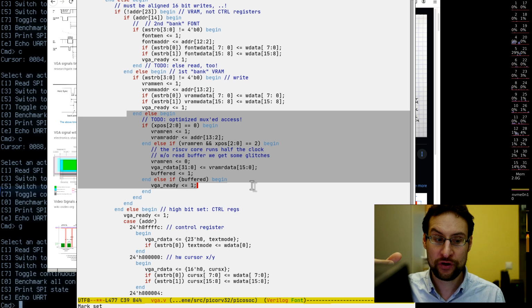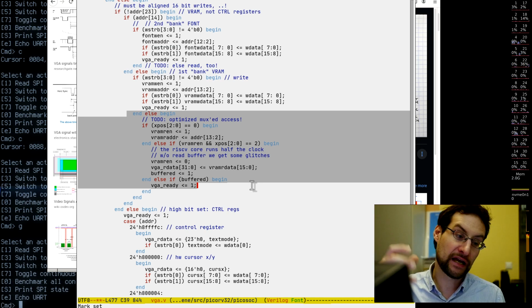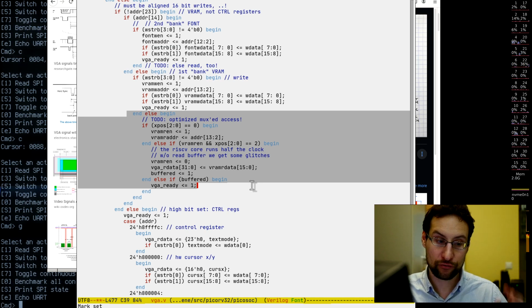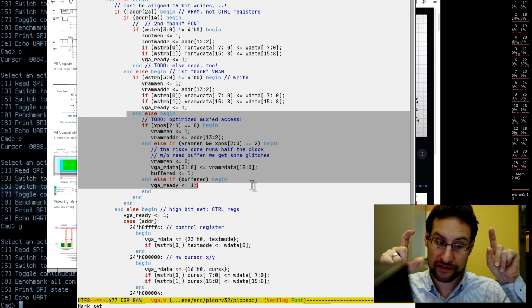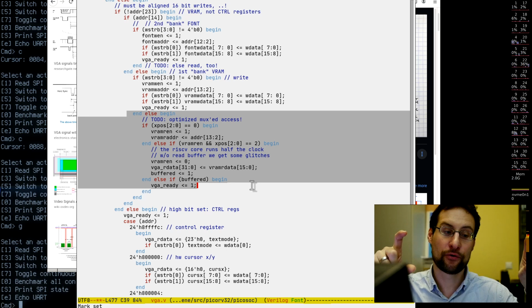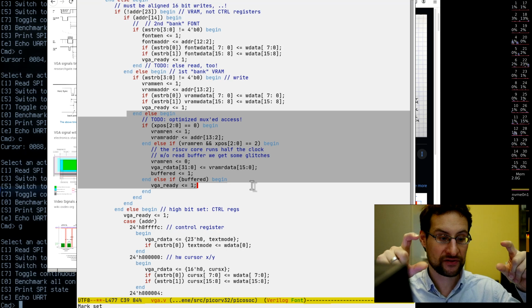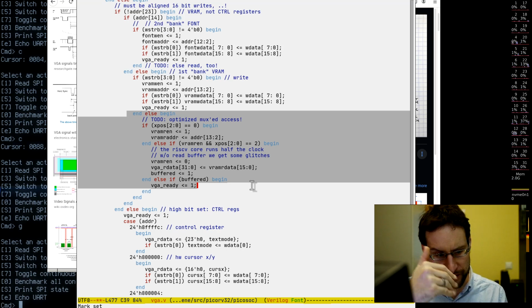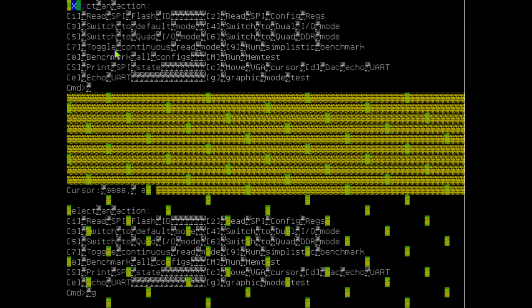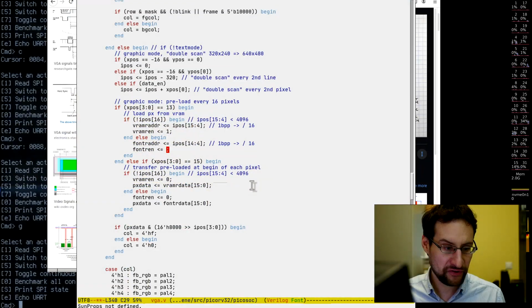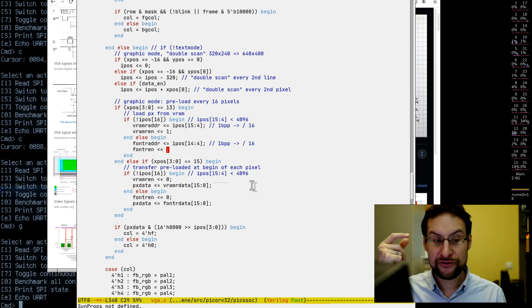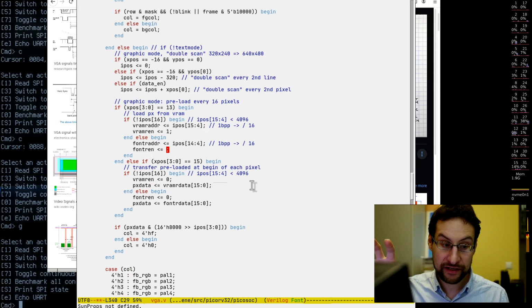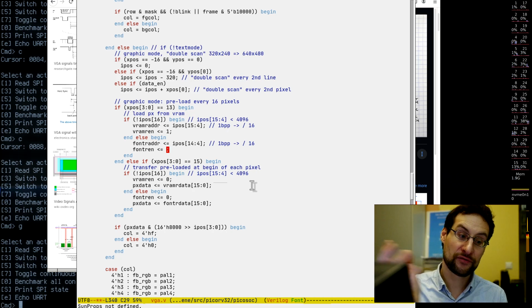I had to learn the hard way that the ICE40 does not have a true dual port memory, so we can only read or write. We cannot have one read port and one write port; they are not full duplex read and write ports. We constantly output a signal to the HDMI output, the video output. Due to that, we need to multiplex our reading, because we constantly read for the video signal.